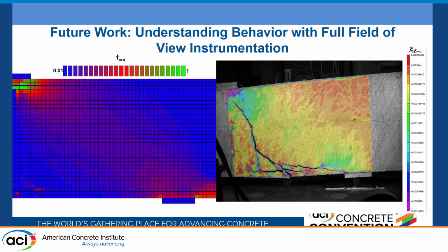assess the different failure modes such that we can have Strut-and-Tie models that can accurately predict what failure mode we're going to have. So this one failed by crushing at the top, although the Strut-and-Tie model predicted it would fail by crushing at the base of the diagonal strut, and you can see that we are able to see the concentration of stresses with our DIC, as well as with a finite element model. We have the crushing captured here, and by completing this study, we'll be able to fill in some of the gaps that have been left with the published literature so far.